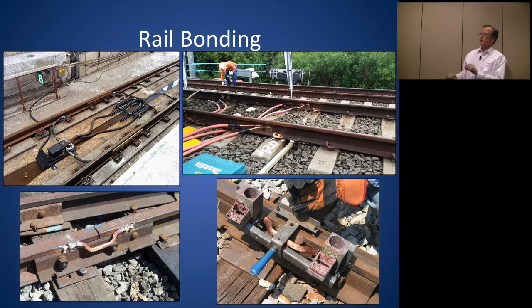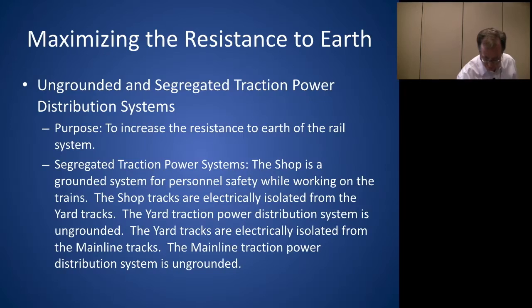It's as much for stray current control because that current is going to get through this, enough of it to run it. It might reduce the efficiency of it a little bit, but if this wasn't bonded here, this could create a pretty high voltage across this joint and cause corrosion to that joint where the current's arcing and jumping across there. It's as much for stray current control as it is for traction power current.